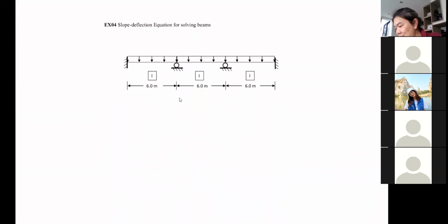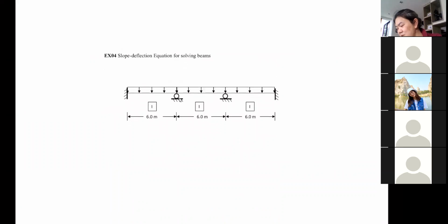Now, we are going to solve the first continuous beam. So it's that beam again, but I don't know if I meant to leave the load out for you guys, because the fixed end formula is WL squared over 12. So I'd suggest that W is equal to 1200 kilogram per meter to ease our calculation. Unless, of course, you like another number. Well, I expected that it's going to be complete silence again. But before we do this, let me show you something.